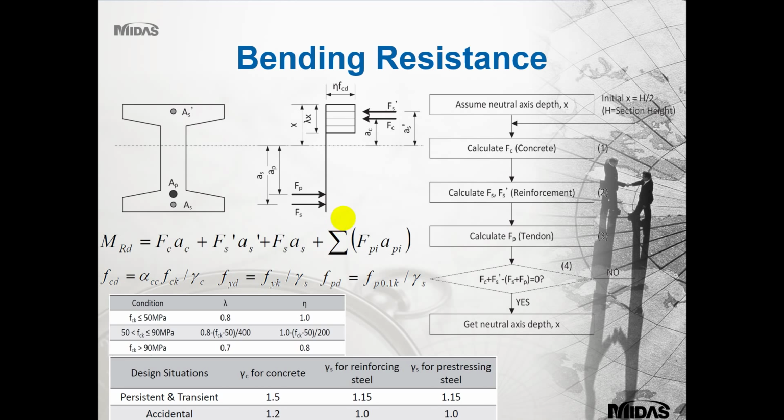So now we're going to look at the bending resistance. We just have to simply calculate as for any other reinforced concrete section. You see the block at the top there, I'll just indicate that with my mouse. The rectangular stress block can be assumed from the Eurocode, and first principles can be used for the moment resistance calculation, which is illustrated in this rather long calculation here.